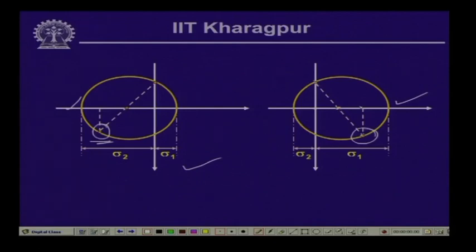This is the center line of the Mohr circle, and the maximum value of the normal stress, represented by this point in the circle, gives you the maximum normal stress or the maximum tensile stress in the member, and this is the value of sigma 2, or the minimum normal stress. This is how we compute from the Mohr circle.